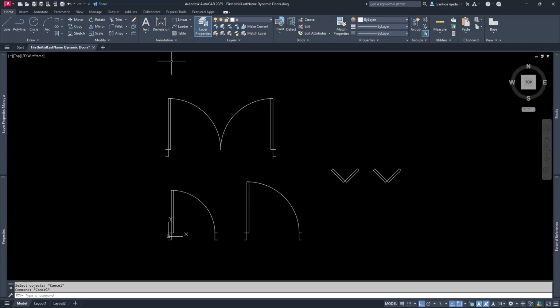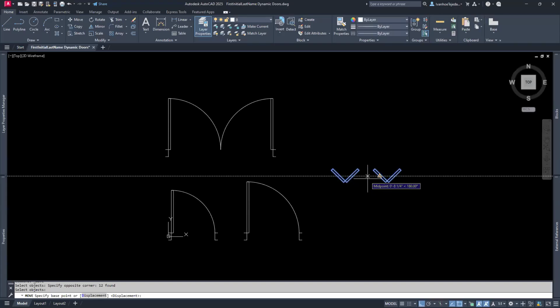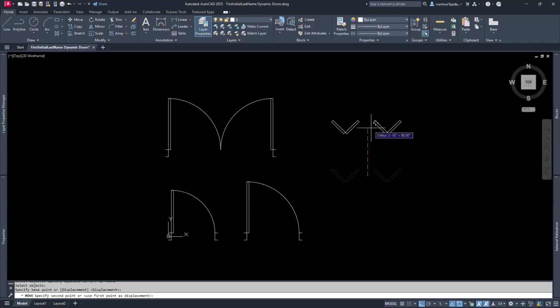Let's say I move these objects, and I'm just reinforcing what I talked about last session. I go to move, select the objects right here, and enter. As soon as I enter, they become part of what AutoCAD calls a selection set. This is the current selection set, these objects here, and it says 12 found. So I click here and move them up to this location. Done.